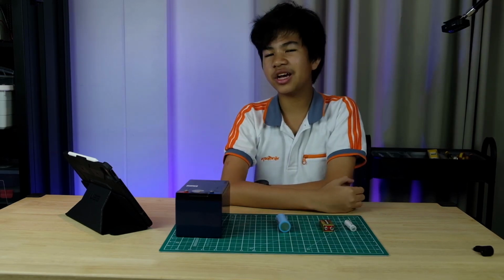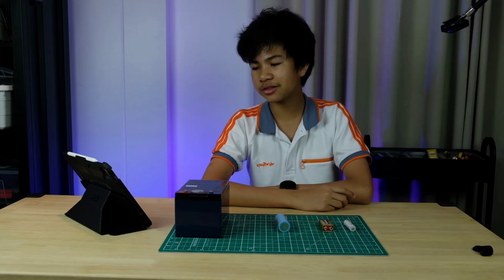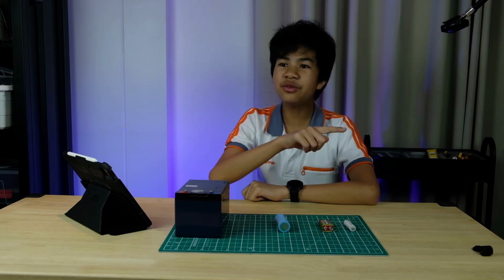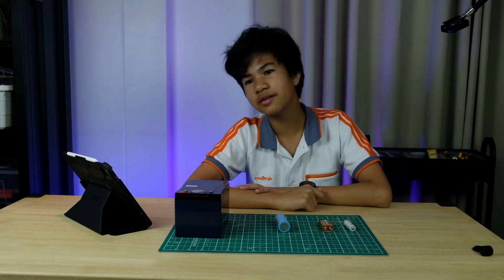The next type is gel. Now instead of those fiberglass sheets, gel uses thick plates. The main difference between gel and AGM is their charging rate. AGM can handle faster charge and discharge rates than gel batteries. So gel batteries are perfect for projects with slow discharge, like maybe a constant motor running. It doesn't work great in peaks; the AGM would be better in that application. But say you're constantly running a water pump, gel works well. So that's a quick overview of these batteries.